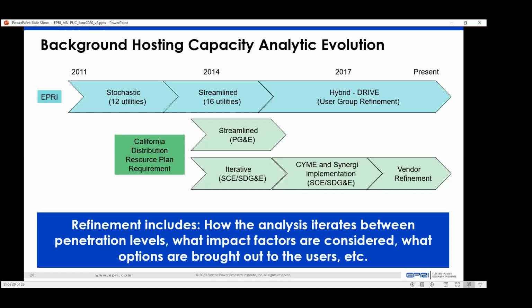I'll say it again, a different way. On one feeder, it'll look at what the hosting capacity assessment in that centralized based allocation was on node X, and it will apply the knowledge of what the hosting capacity was there when it starts the analytical analysis on node Z. So there is a learning part within these analytical engines that says, well, what do I know about this feeder already to start and refine my analysis and evolve these analytics within it?